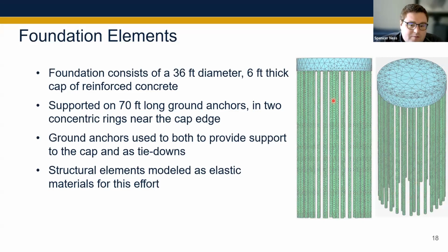Importantly, in this foundation, one of the complications that we had was that some of these ground anchors provide direct support to the cap, acting effectively as piles. Some of them are acting as tie downs, which creates a unique mechanism that we've been working to model in this effort. And I think we've come up with some better ways to approach that since we completed this effort, that we'd like to iterate on this process and see what impacts that might have.